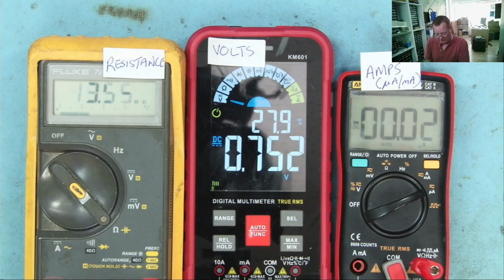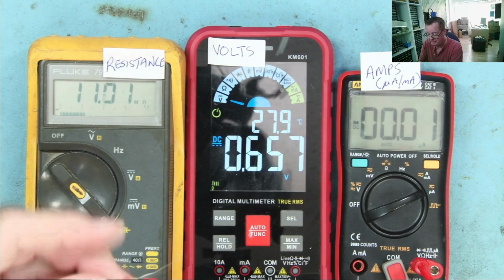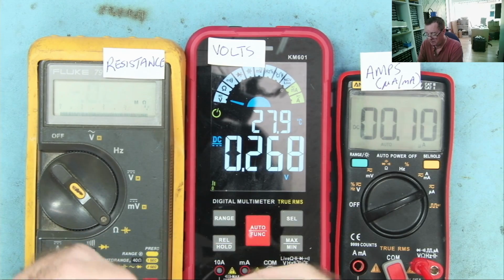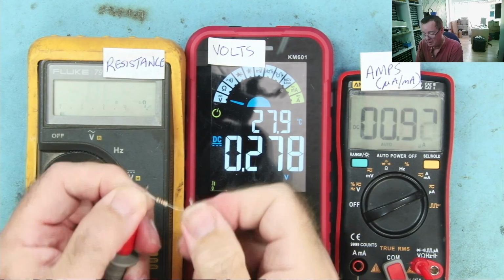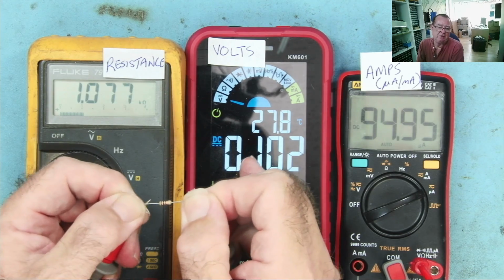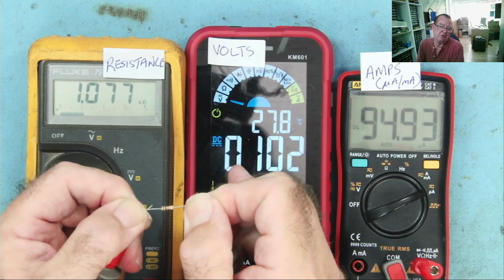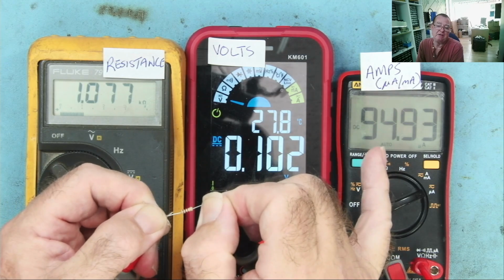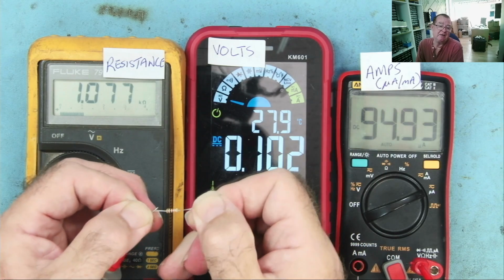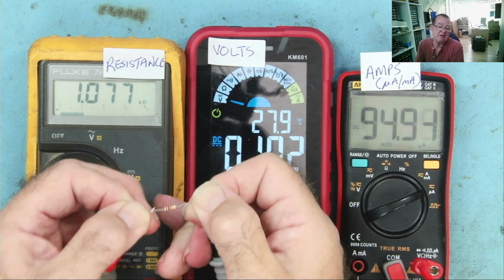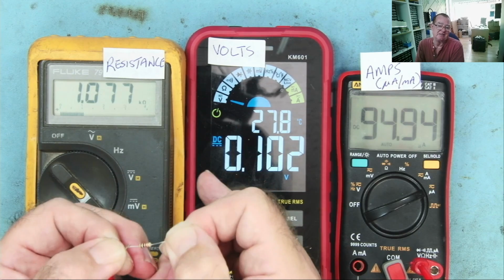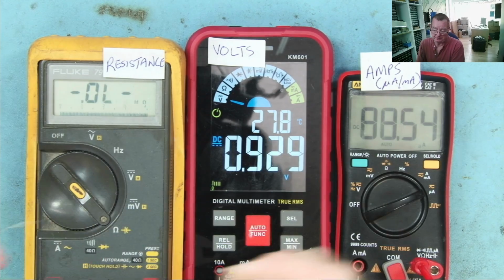Okay. If we now take a 1k resistor and we do the same thing. Okay, 1k resistor, what happens? Well, this meter's still generating 0.1 volts basically, okay, 100th of a volt less, but very close. This is now passing 95 microamps, and this is reading just over 1k. So you can see that the meter, in resistance mode, is a constant voltage source. The voltage generated stays the same, and it measures the current.